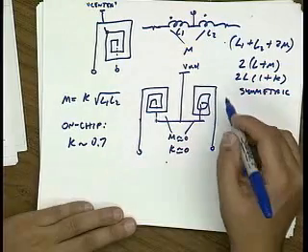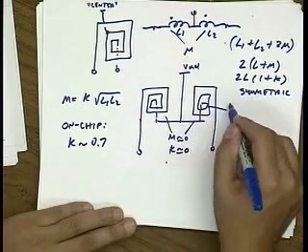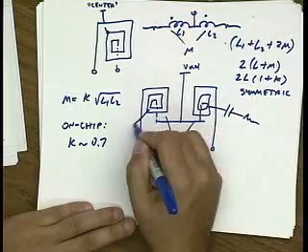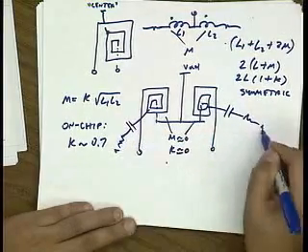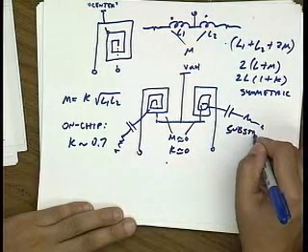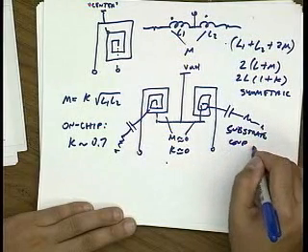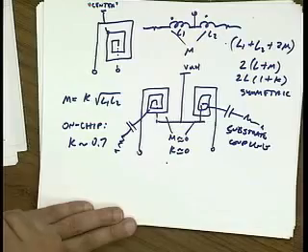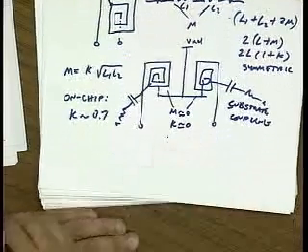And because the bigger you make these windings, the more they couple to the substrate, they're going to actually have lower Q values. So this is due to substrate coupling. Okay? Questions?